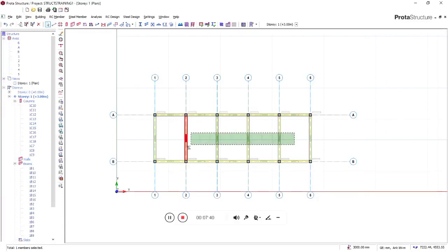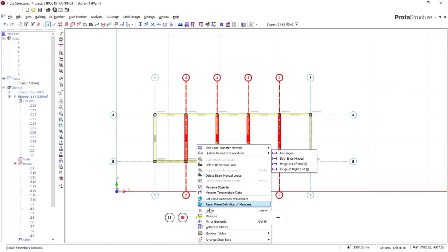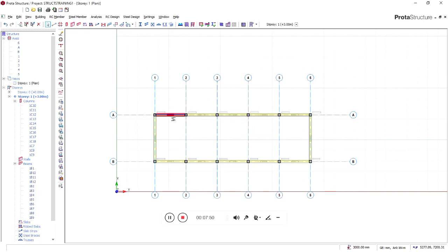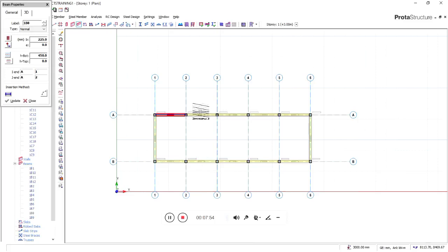Let's delete what we have done now. I'm not deleting everything, it's only the beam I'm deleting. Properties. So look at it very well, please. First point, second point with left click. Now you want to escape this point. If you had come here now, it will just draw this beam diagonally, which is wrong. So what you should have done is this.